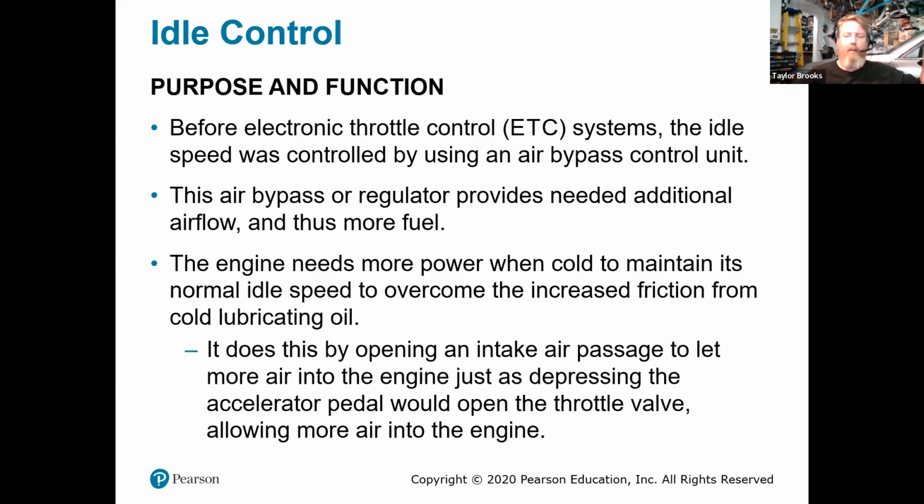Now, the last thing to talk about with fuel injection is that when we have a carbureted engine, we have to manipulate or restrict the airflow when the engine is cold. You may have heard this term as a choke. What choking is, is restricting the amount of air coming in to basically richen up the fuel air mixture so that the engine remains running at colder temperatures. We also, because a carburetor is using engine vacuum to basically come off of fully closed on its needle and seat, and allow for the engine to run,